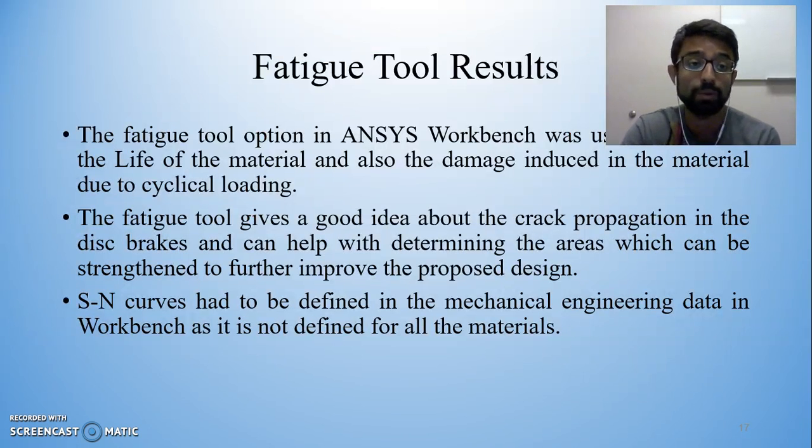Moving on to the second part of my analysis, this is the fatigue tool results. So the fatigue tool option in Ansys Workbench was used to evaluate the life of the material and also the damage that would be induced in the material due to cyclical loading. The fatigue tool gives a good idea about the crack propagation in the disc brake, which is the location where the crack propagation might start for a particular material, and can help with determining the areas that can be strengthened further to improve the proposed design.